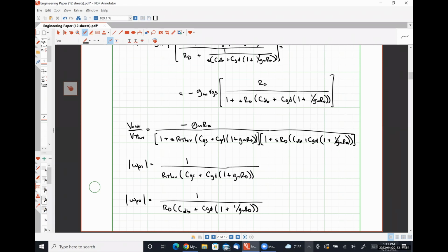This is an approximation, okay? In doing this, we somehow magically got rid of a zero, right? If you look back at our direct analysis where node G and node D were linked together by that capacitance CGD, we absolutely still had two poles that were effectively coupled together. We had a quadratic response that we needed to figure out what those values were. But we also had a zero in our numerator that we had to contend with.